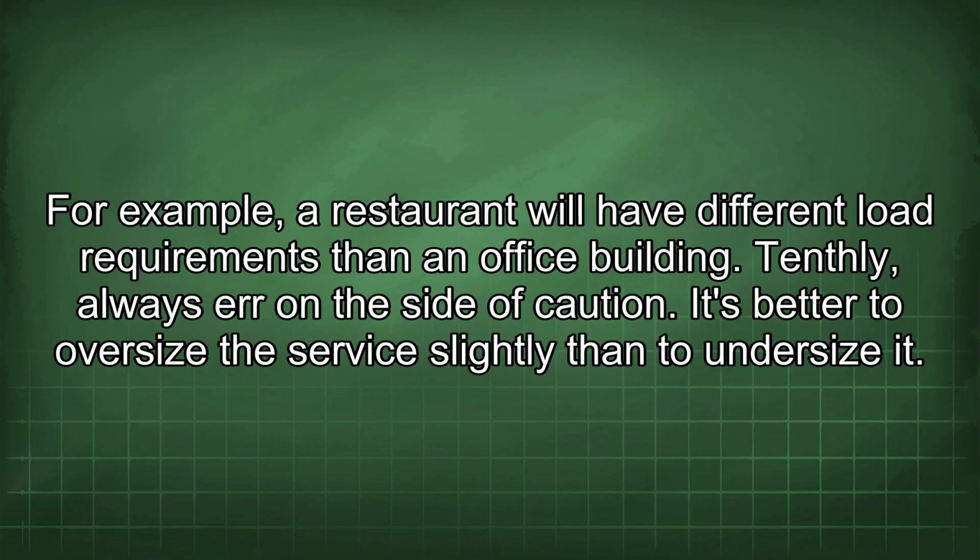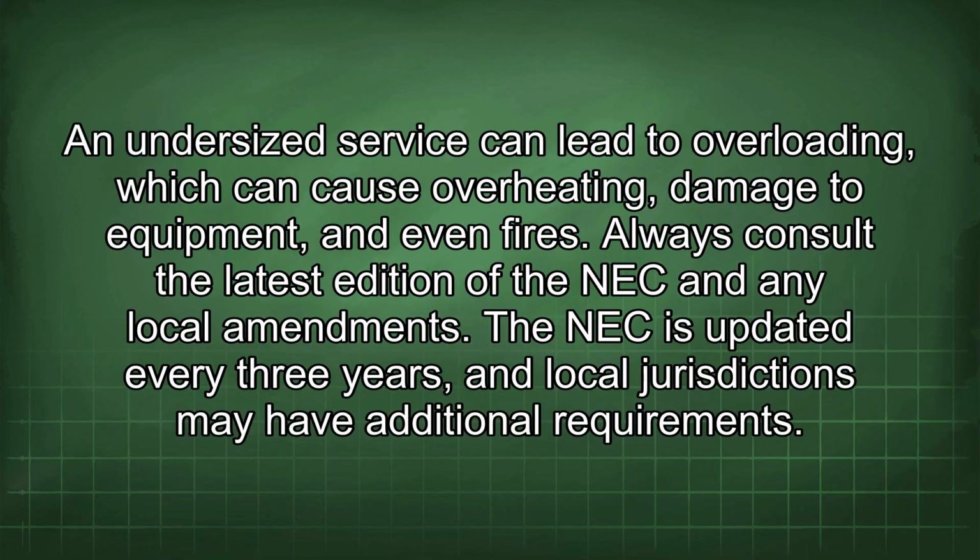Tenthly, always err on the side of caution. It's better to oversize the service slightly than to undersize it. An undersized service can lead to overloading, which can cause overheating, damage to equipment, and even fires. Always consult the latest edition of the NEC and any local amendments. The NEC is updated every 3 years, and local jurisdictions may have additional requirements.